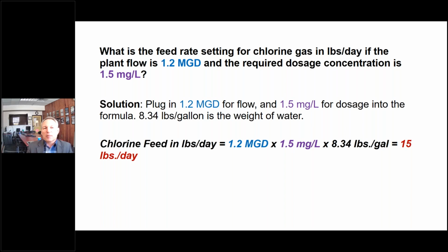And I want you to think a little bit about how this applies to the slides we just saw about dosage and residual. Our dosage is 1.5, but the residual that we measure in the water is going to be a little less, isn't it? Why? Because there are going to be some reducing compounds in the water and possibly some nitrogen compounds that combine. So who knows, it depends on the water that you're trying to disinfect. The residual will be a little less unless it was pure deionized water.